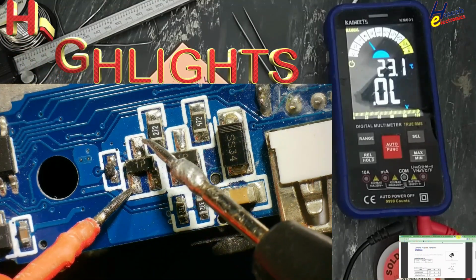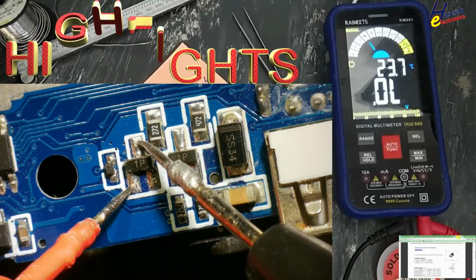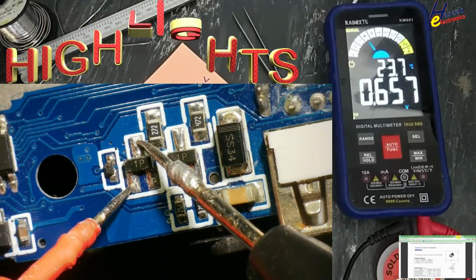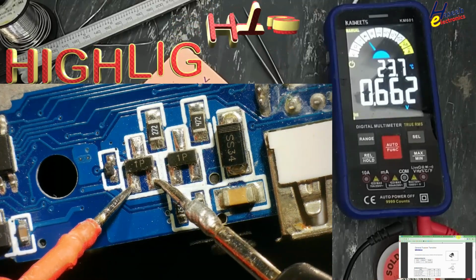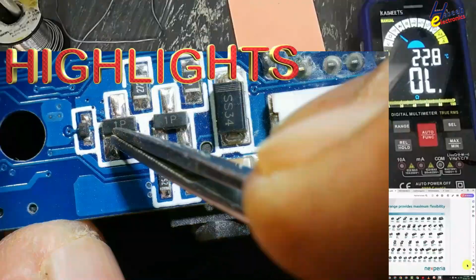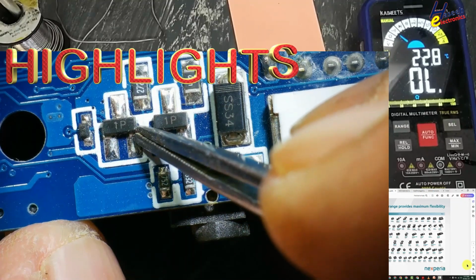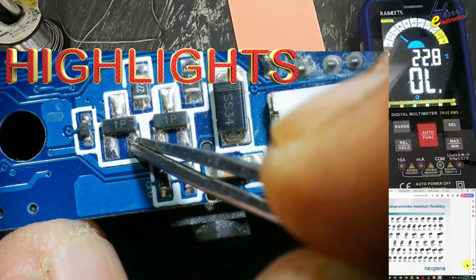0.663, 0.658. This value is low, that means it is collector, and this value is high, it is emitter. It is an NPN transistor. How to decode this SMD marking and find its part number and its datasheet.